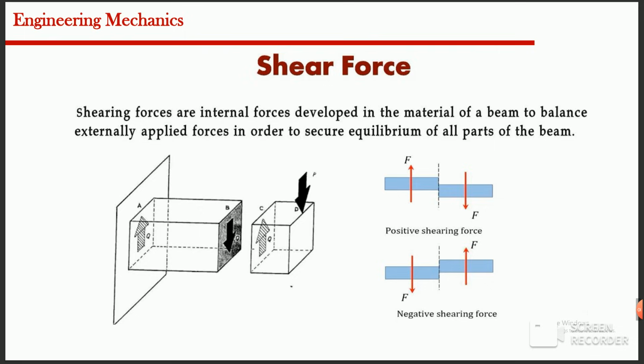Let us first understand the meaning of shear force. Whenever external loads are applied on a beam, internal forces are developed inside the beam to maintain equilibrium. One of these internal forces is called the shear force. The shear force at any section of a beam is defined as the algebraic sum of all the vertical forces acting either to the left or to the right of that section.